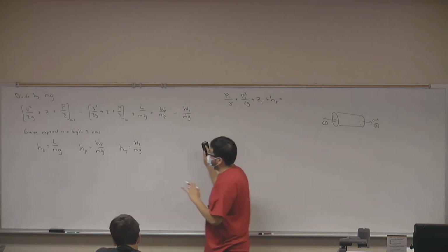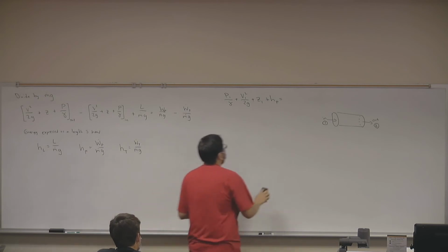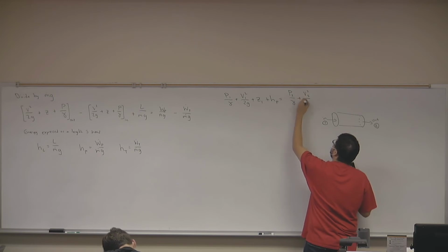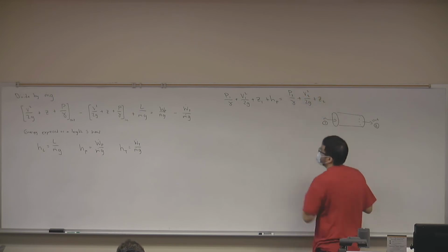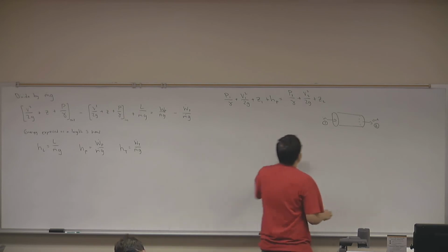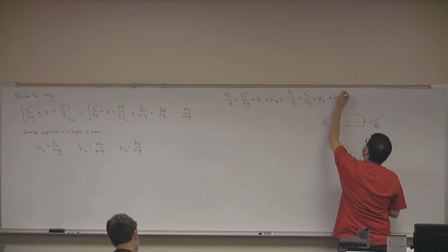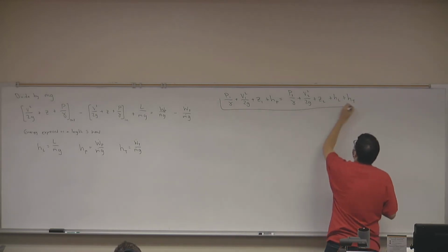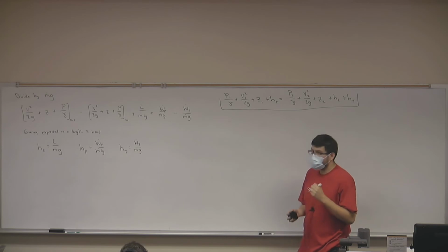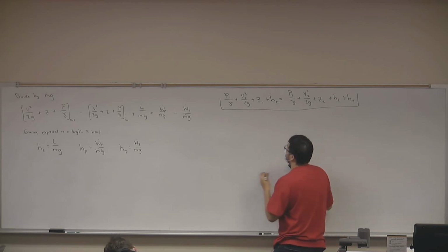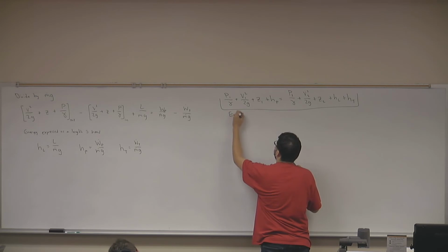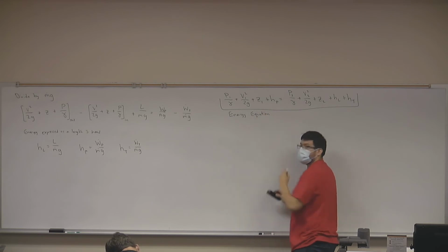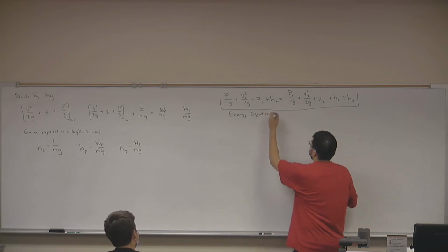And then I'm going to move everything else to the other side, so we have our exit terms. Again, pressure, velocity, elevation. I'm left with my losses and my turbine head. And this wonderful, simple, easy to use, length dimensionalized equation is what we call the energy equation. Ta-da! For steady uniform flow.